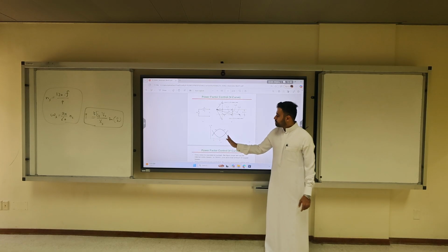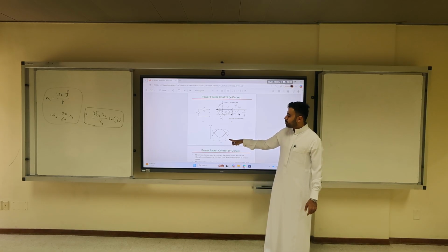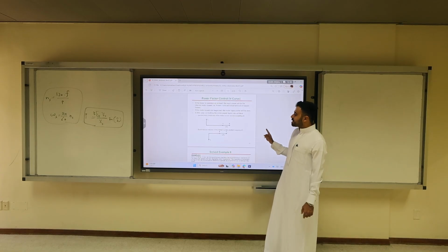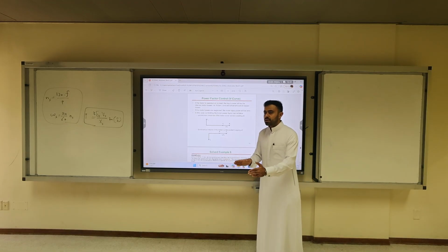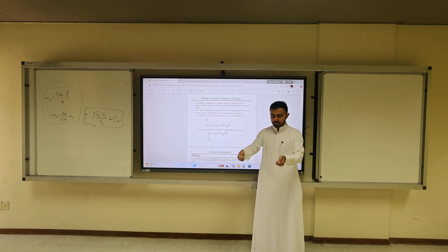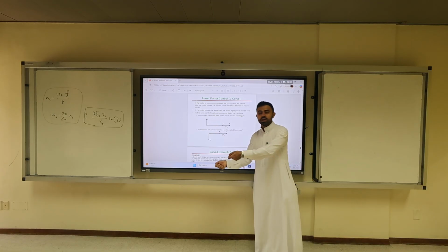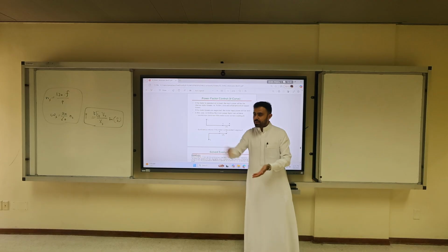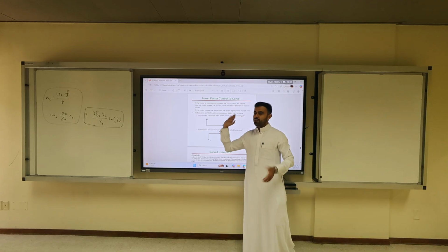However, in these two applications, if you notice, you become all the way the largest amount of Ia, all the way to 0. But this is just for a pure synchronous condenser. The moment you connect it to the grid, you will have an angle of Ia. Get it? As a synchronous condenser standalone, it will be 90 degrees Ia with respect to Vt. The moment you connect it to the grid, it's a function of nearby loads. Get it? So this Ia will be somehow like that for the whole system.